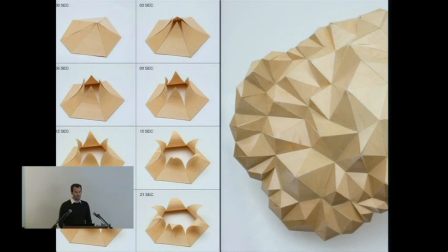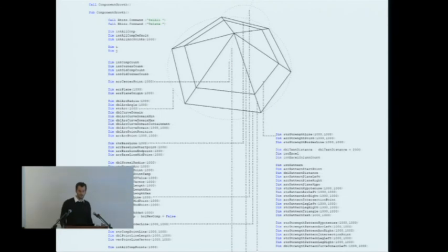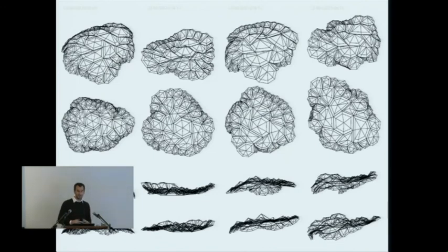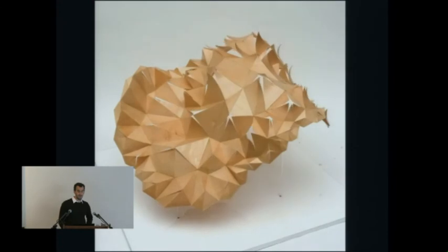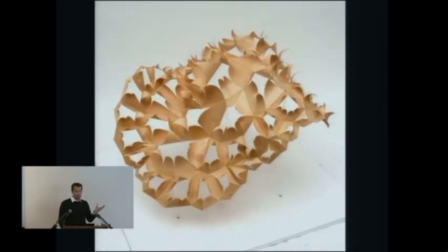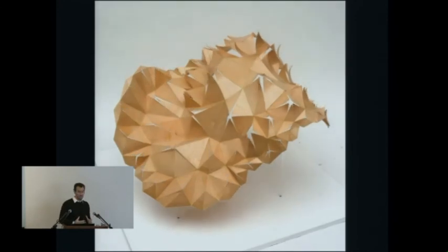So at the same time, and accounting for the more complex reciprocity of the individual elements as well as the overall system responsiveness, we have developed a more adaptive system and related computation design process in order to derive more specific system morphologies. So in this process, the surface geometry is algorithmically generated and controlled through a number of parameters and constraints actually based on the material's anatomy, the characteristics and behaviors, resulting, in this case, in a fully functional prototype. So here, the veneer composite pieces are, at the same time, sensor, motor, and regulating elements.